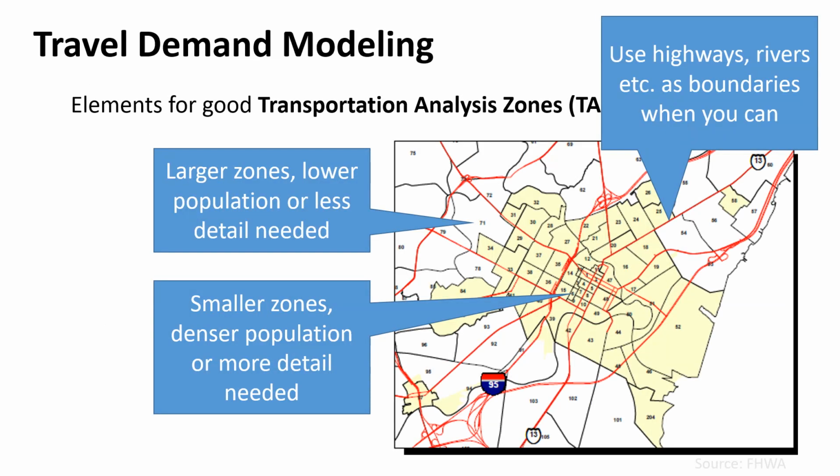So now jumping back to where we left off last time, back to these transportation analysis zones. We were talking about how we break a region by geography into zones of similar sizes and similar uses within it. Hopefully 37 is mostly all residential, whereas these smaller ones are probably the downtown area. Maybe they're all more commercial.